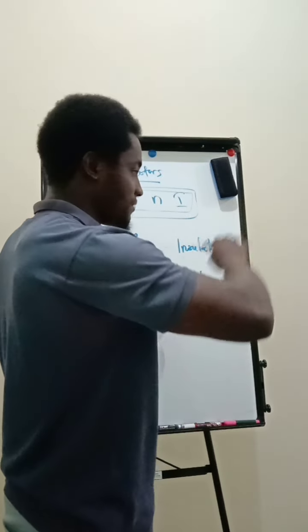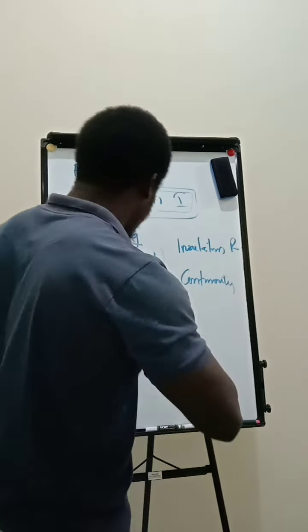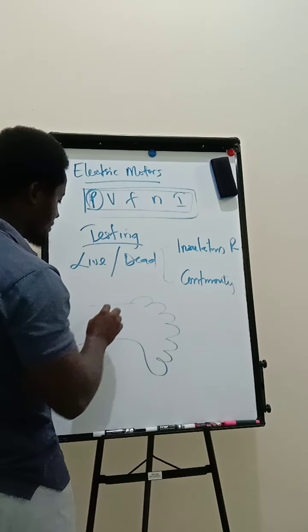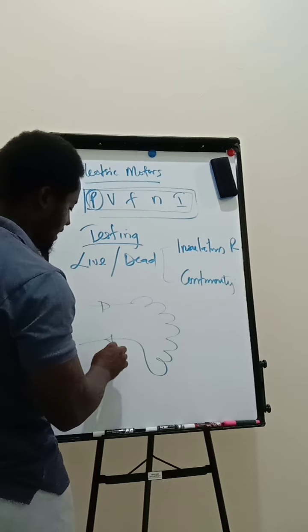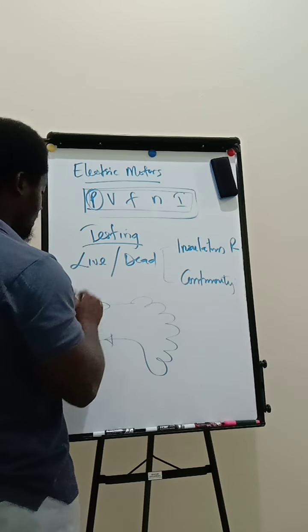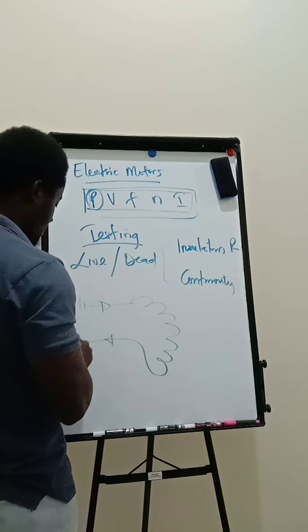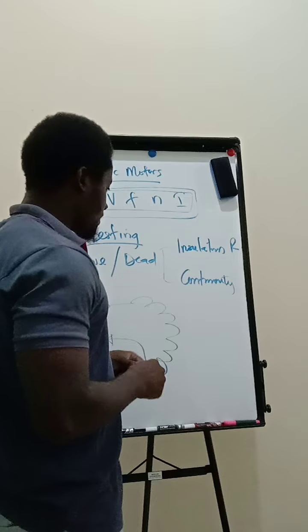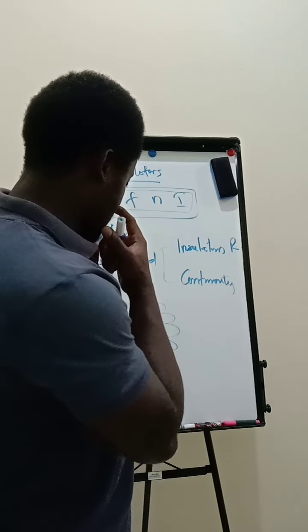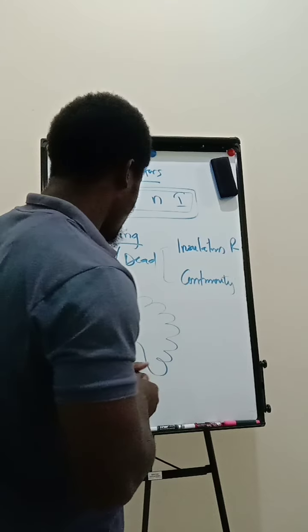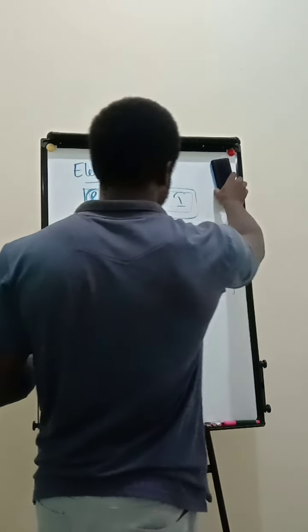So the winding we rewind in the electric motor leaves, coils, and then comes back. So we have the start and then we have the end point. So we will be able to identify this set of winding as either U1 and the other will be U2. As such, we are going to identify all the other windings, like the U windings, the V windings, as well as the W windings, the start and the finish.